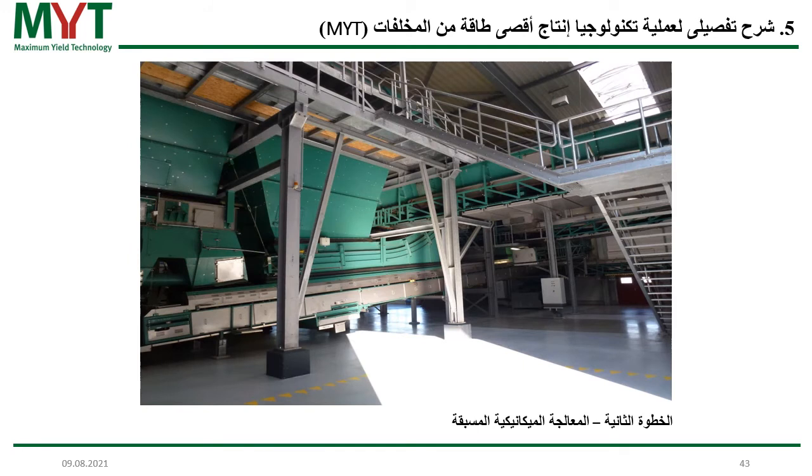Now you have an insight into step number 2, the mechanical pre-treatment. In this technical setup for Kahlenberg, it looks like the following. You have a big sieve drum with bag openers. I'll show you in the picture on the next slide. You also have ballistic separators for separating the heavy and the light fraction, and we have 2 manual sorting cabins in this setup. One sorting cabin is checking the sieve overflow, so the big parts of the waste, and the other sorting cabin is checking the middle fraction of the heavy fraction from the ballistic separator.